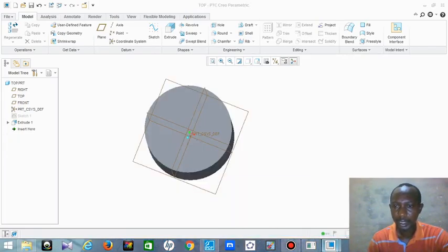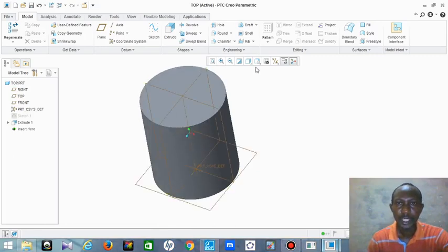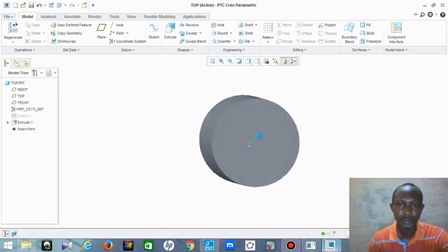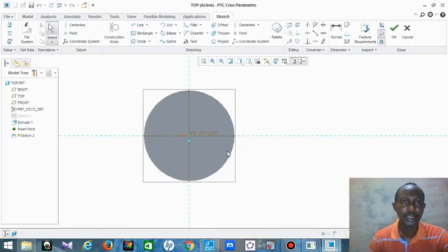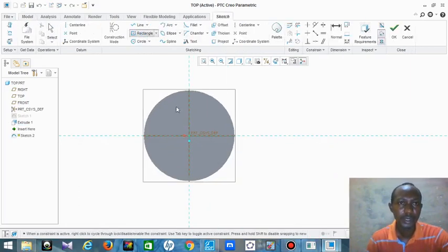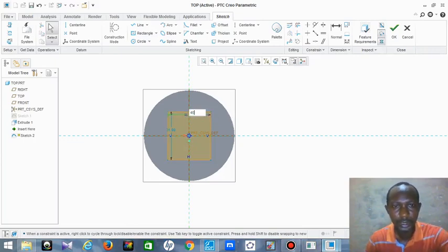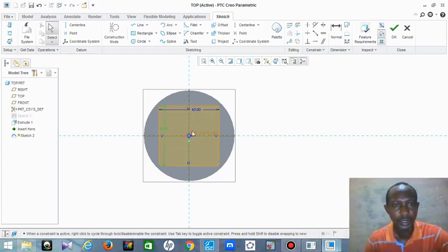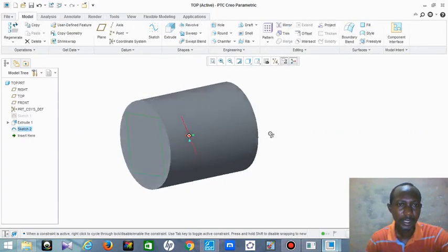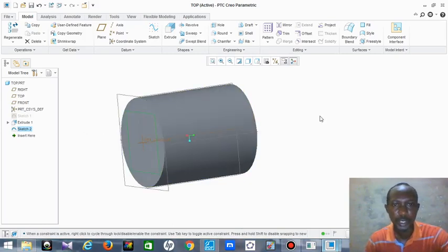So this is where I am now. Okay, so under the bottom, let me look for the bottom. Okay, you click it, sketch, then what next? You make your rectangle at the bottom, and this rectangle should be 40 by 40. 40, and double click by 40. Okay, this is what I want to do. Then okay.